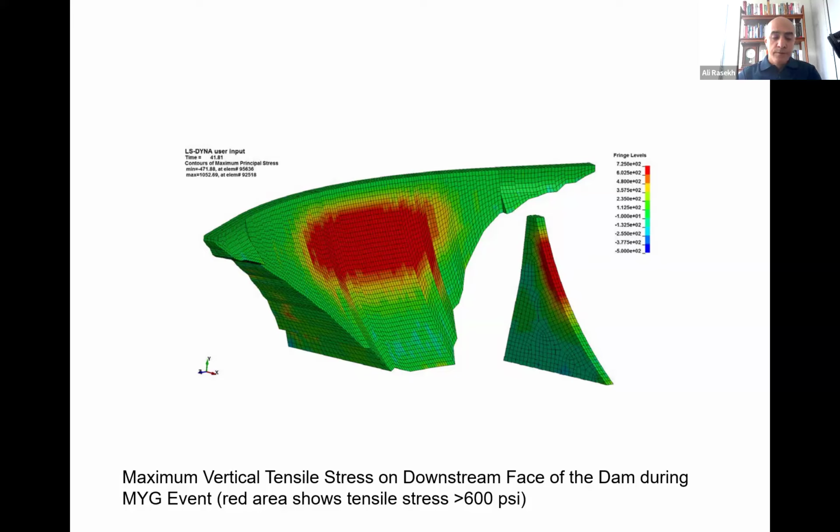However, you should look more carefully at their extent. Do they cause failure? We are not looking for overstress zones; we are looking for failure modes. The question is, does this dam fail after this earthquake? We cannot say that because some local overstress was there, it definitely fails or doesn't fail. So we should look at that more carefully. That's generally what I can say for all dams.